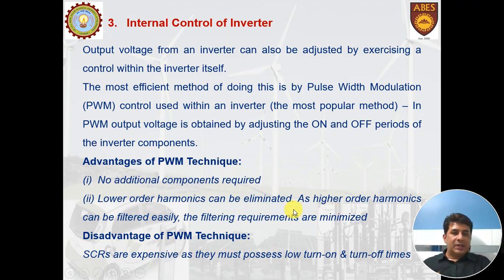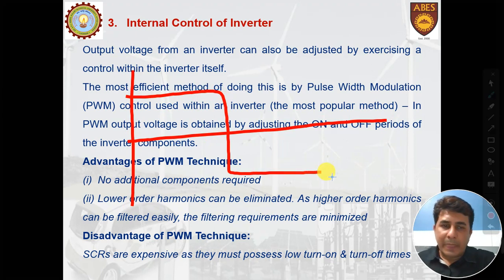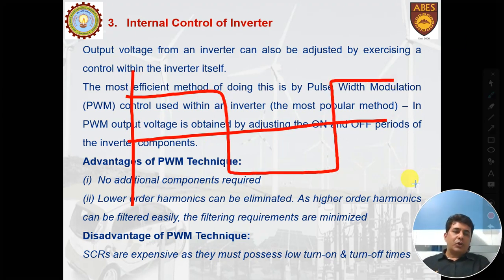Now, harmonics: whenever we are using a power converter or an inverter, it introduces harmonics. As I said, the output waveform of the inverter is a kind of rectangular wave. You might have noticed, if you have an inverter in your home and that inverter is not a sinusoidal inverter, then whenever you are switching on your devices, you hear a humming noise coming out of them.